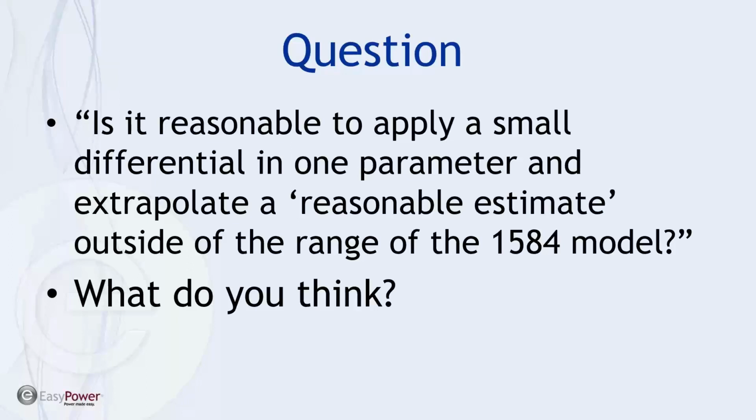The thing to really consider is the difference between horizontal in a closed box and vertical in a closed box. It has nothing to do with the direction of the bus itself. In other words, if I have 3 buses running horizontally and they do not have a termination that points out at the operator, then that should be classified as vertical in a closed box.